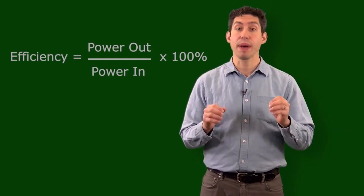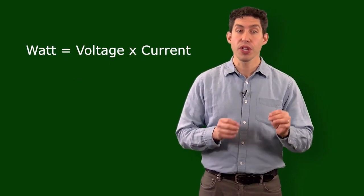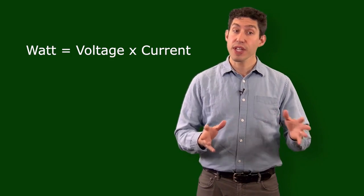Efficiency is defined as the power out divided by the power in multiplied by 100. For photovoltaics, that's typically measured in units of watts per square meter. As a reminder, a watt is electrically equivalent to voltage multiplied by current. For sunlight, we measure irradiance, or wattage per square meter, using something like a pyranometer. Generally, this is done using a portable power meter or under standard test conditions.